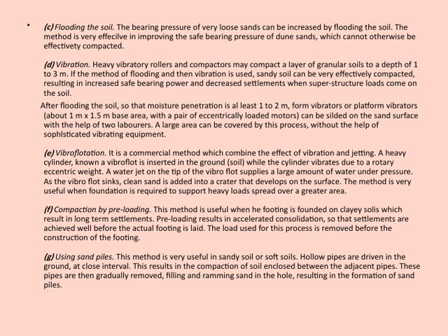Finally, we have the use of sand piles. This method is highly effective in sandy or soft soils. It involves driving hollow pipes into the ground at close intervals. The soil between these pipes gets compacted as the pipes are driven in. Then, the pipes are gradually removed, filling the resulting holes with sand that is rammed in to form sand piles. These piles act as reinforcement, increasing the overall stability and load-bearing capacity of the soil.